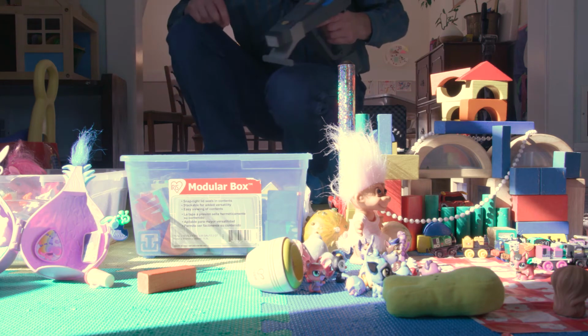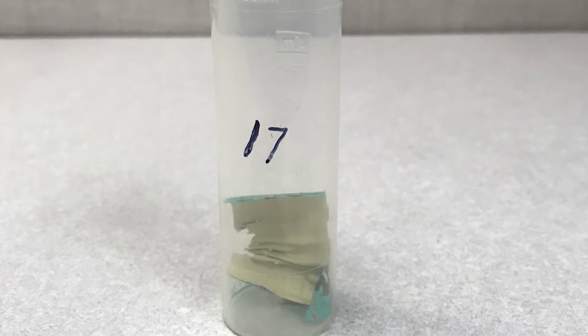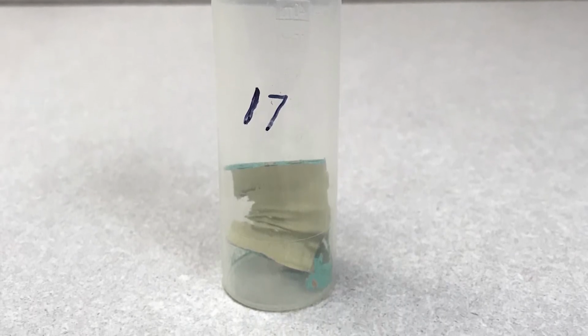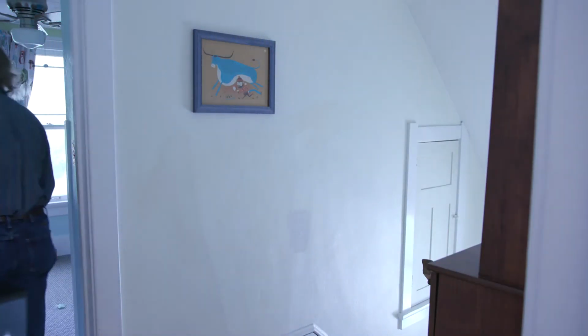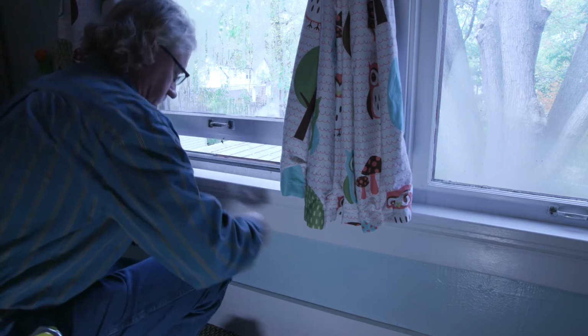As mentioned earlier, paint chips are intended primarily to verify an inconclusive reading from an XRF or to test paint in dwellings with very limited deterioration. If there are a large number of locations that will need to be tested, paint chip sampling is not recommended. When selecting a location to take a paint chip sample, always look for areas that are the thickest and give complete paint history of that component. Many times, this may be on the edges, top, or bottom of a component. These areas are also less visible since paint chip sampling is destructive to the surface coating.